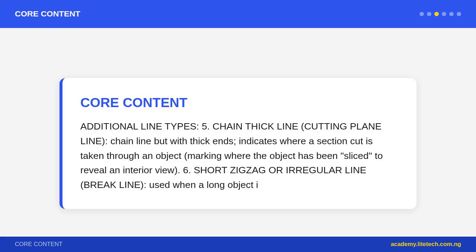Drawing lines at standard angles, using T-square plus set squares. Horizontal lines: T-square alone. Vertical lines: 45 degree or 60/30 degree set square with blade against the T-square. 45 degree lines: 45 degree, 90 degree set square with hypotenuse as guide.